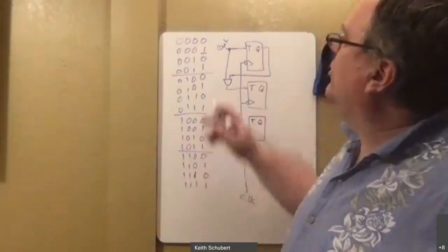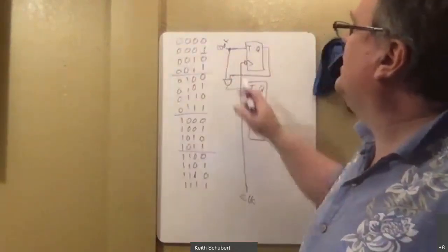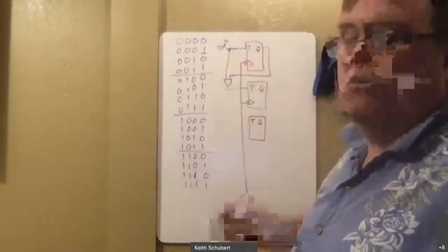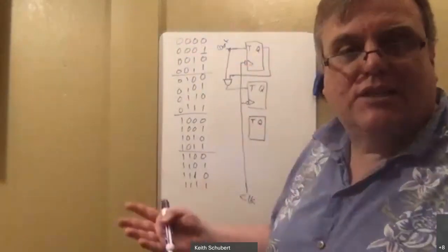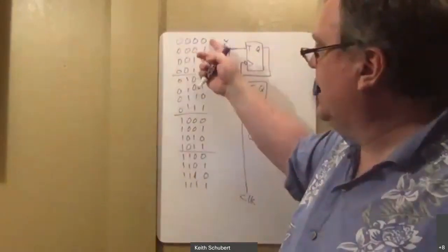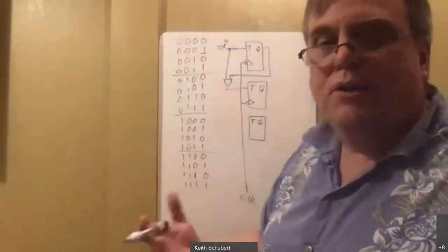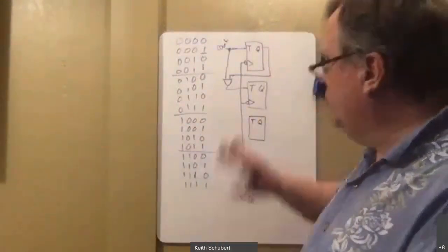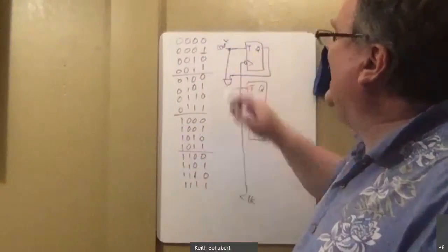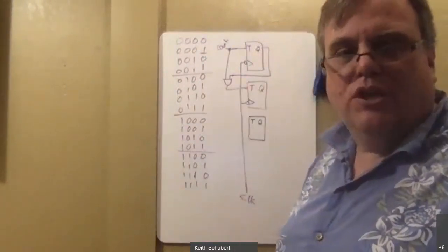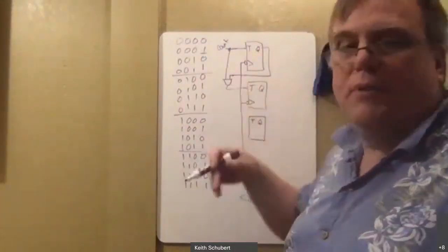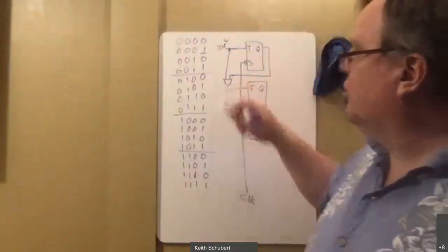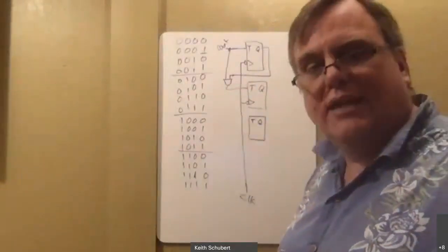And all you'd have to do, in addition to the possible states here, is add count. That's my input signal. So then I'd have 5 signals, 4 states plus one of those. I can make a 5-variable Karnaugh map. I could do the encirclements, and I would get that AND gate for the T flip-flop. I just have to do the T flip-flop excitation table to make the Karnaugh map. I could do the encirclements, and it will reduce to that nice little AND gate.